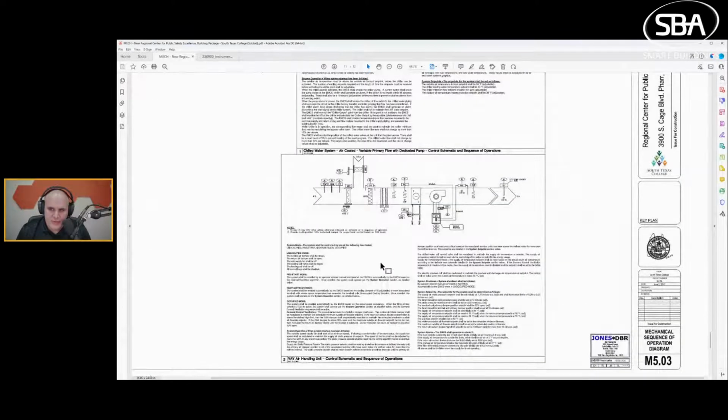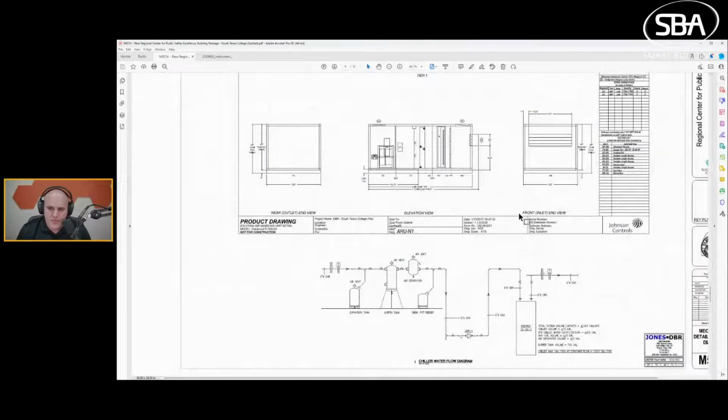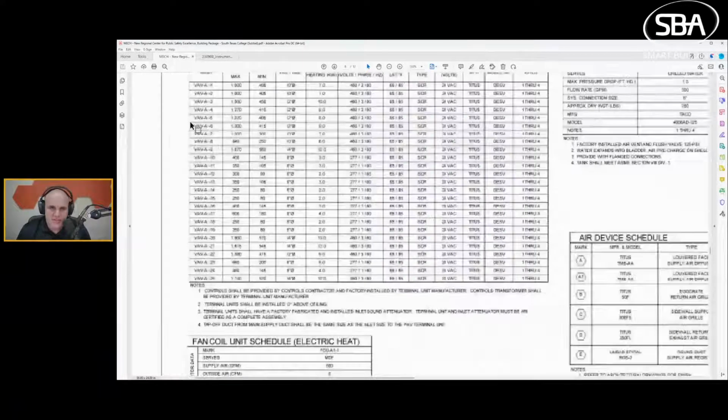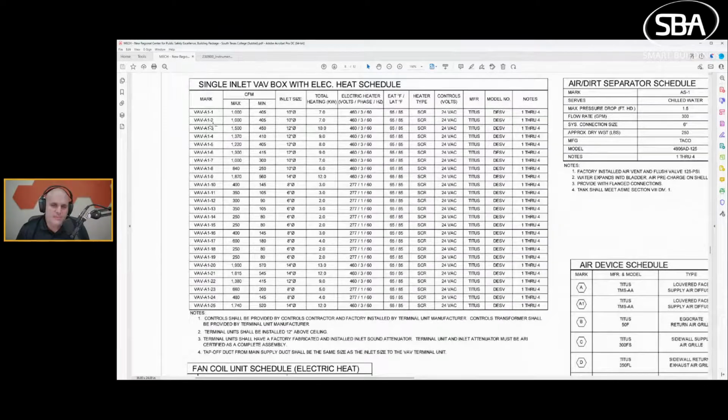Now, once we understand our one lines and we've got our count of inputs and outputs for each system type, we will then go up to the schedule and get a count of systems. So for system type VAV, we have 25 VAVs. So we would build out our input output list for the VAV, and then we would just say, okay, we got 25. So whatever that count is times 25, that gives us our count. That's typically how we get our count.